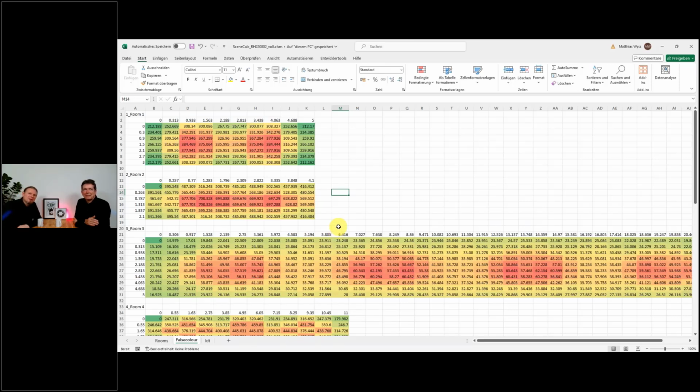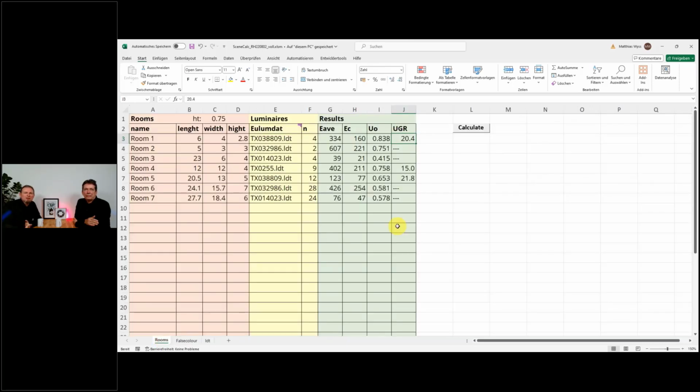Of course, if you have a CAD application, it makes more fun. Or if you have a design office where you have some BIM applications, or if you can use APIs and you have applications with room geometry and luminaires, then you can easily loop this thing and find your own optimizations in terms of lighting designs, and you get the Relux results directly in code, in XML, back on your desk, and can have your investigations on the best performance, on the best luminaires for your situation based on real photometric calculation.